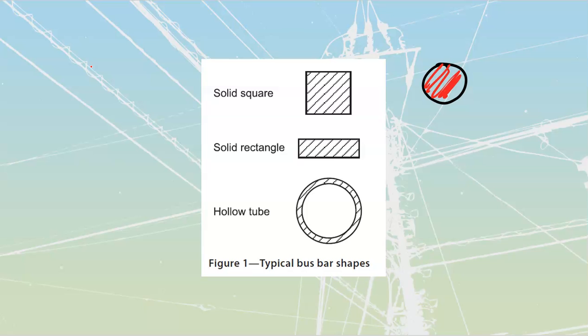Most of the time, we deal with conductors that are going to be annealed. Annealing is where the hard drawn conductor is then heated up. And as it heats up, it is going to soften back up again. And then it makes it easier for us to bend and drag it in through holes that we've drilled through the studs and everything else.